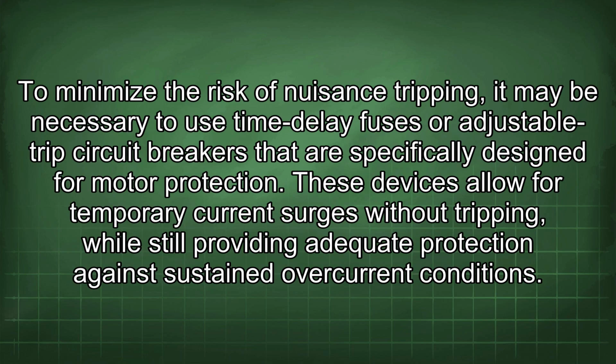To minimize the risk of nuisance tripping, it may be necessary to use time delay fuses or adjustable trip circuit breakers that are specifically designed for motor protection. These devices allow for temporary current surges without tripping, while still providing adequate protection against sustained overcurrent conditions.